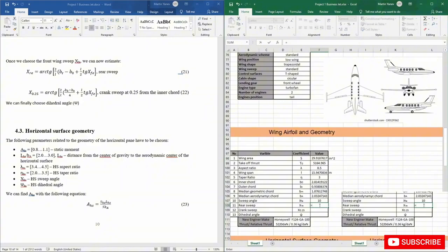So here this will be equal to ATAN, which is arctangent in Excel, and then bracket 2 divided by L multiplied by bracket BR minus B0 plus L divided by 2. So now we have L divided by 2, and then we multiply all this, and actually I will put it in brackets so we ensure that this is a closed calculation.